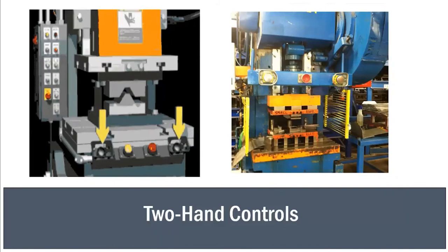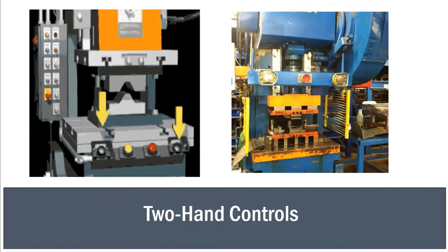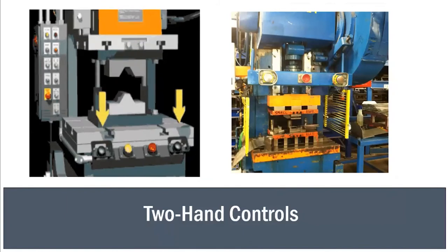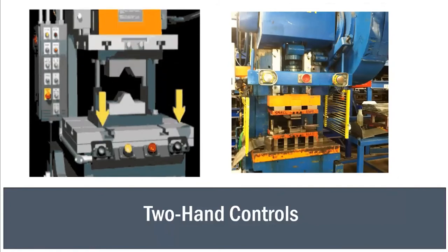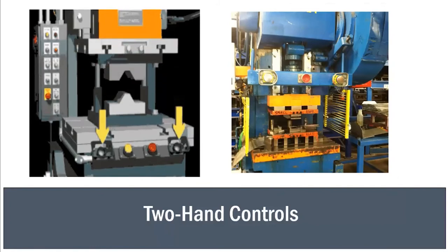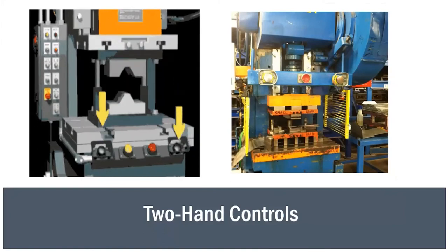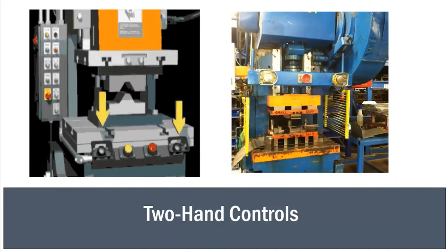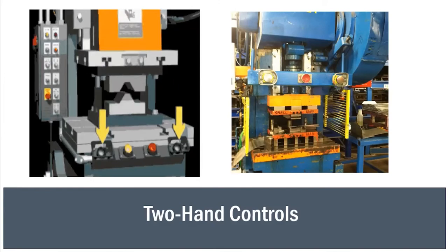So as I say, an emphasis: test the controls. Every time you see two-hand controls, particularly stuff that's been retrofitted to a machine, you want to verify the function. This press here on the right, these obviously came and were designed for that press. I see often people have retrofitted a couple of buttons on the front of the machine that are, quote unquote, two-hand controls, but then you really test them and they don't function as such.